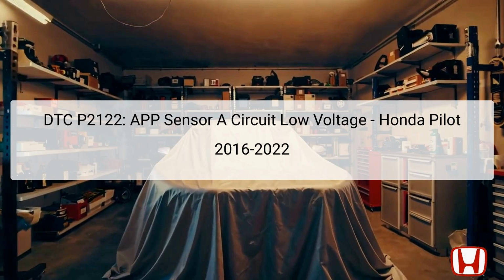The DTC P2122, identified as an APP Sensor A circuit low voltage issue, is significant for Honda Pilot models produced between 2016 and 2022. This diagnostic trouble code, DTC, refers to a condition where the Accelerator Pedal Position (APP) Sensor A, also recognized as Throttle Position (TP) Sensor D, does not provide the expected voltage level. Under normal circumstances, the signal should register above 0.2 volts.